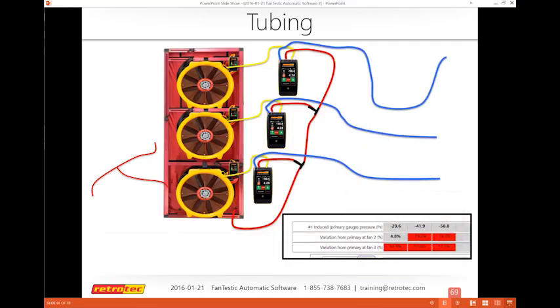So if I did decide to separate my individual tubings to, say, different floors or different parts of the structure, so I can confirm that I was getting good pressures on the 8th floor as the 4th floor and the 1st floor, these are things that can actually happen in the report the software generates. It can say, wow, your fan number 2 and fan number 3, their pressures are too far off in the room compared to what your main gauge is.